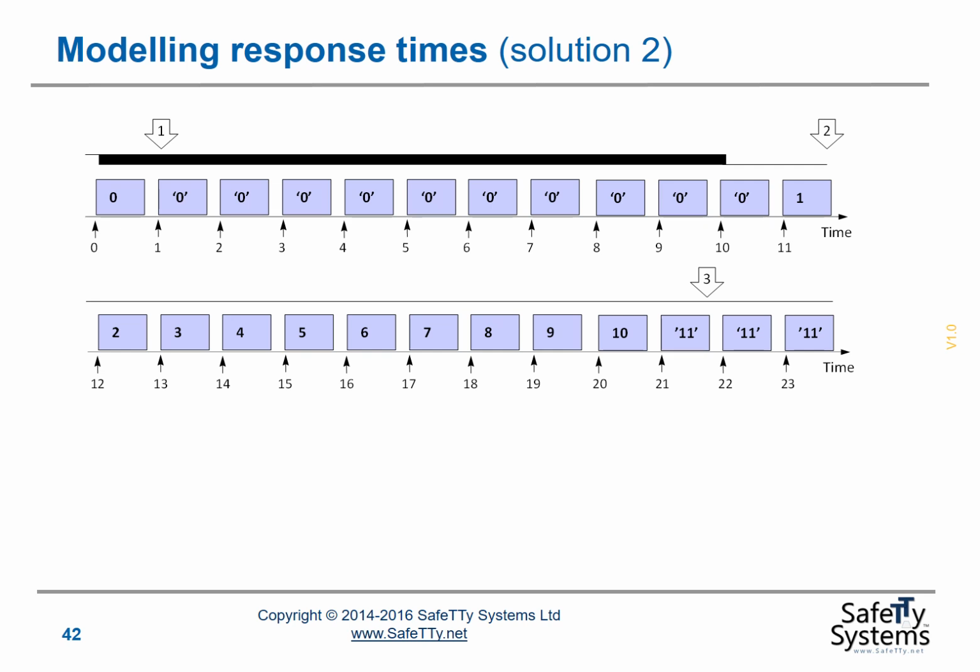So our total time here is 21 milliseconds plus the worst case execution time of the switch update function, plus we will also have to add on the worst case execution time for the emergency stop update function, which will give us a total of 21.2 milliseconds for the response time in this case.